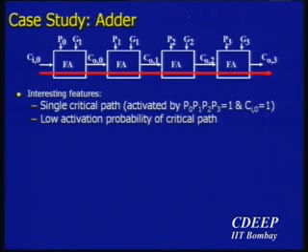So if I were to scale my supply voltage down to the level that I change my long paths now from 0 to 8, and then from 9 to 15, then what happens is when it comes to 2-cycle operations, probably 75% of the time I have to do 2-cycle operations, because I'm looking at bit number 8, 0, 0, no carry propagation, I'm fine. I can do single-cycle operations, but as soon as something else happens, I'm in trouble, right? And I need a very simple decoder. The decoder is nothing other than detecting 0, 0.